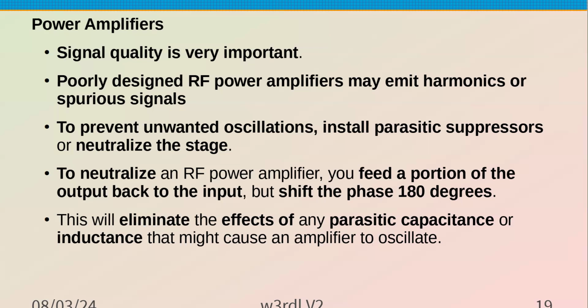So that pretty much will take care of the parasitic capacitance and inductance that is going to be in the output device. That you can't get away from because we're using real world components, inductors that have interturn capacitance, capacitors that have inductance in the lead. So it's not a nice RLC circuit. It's a mini RLC circuit.